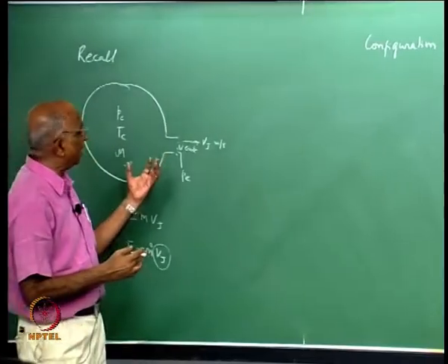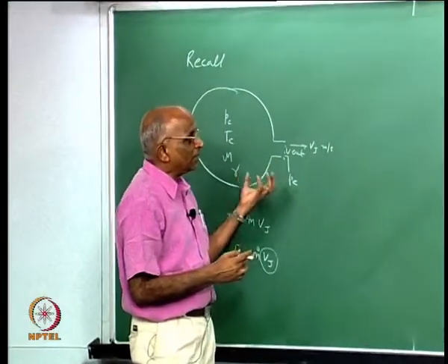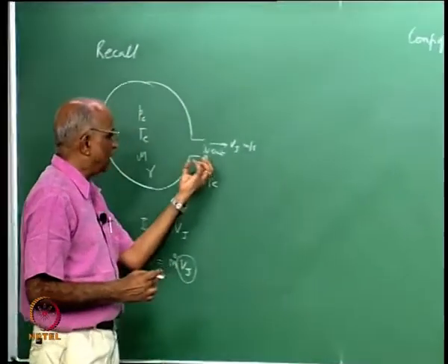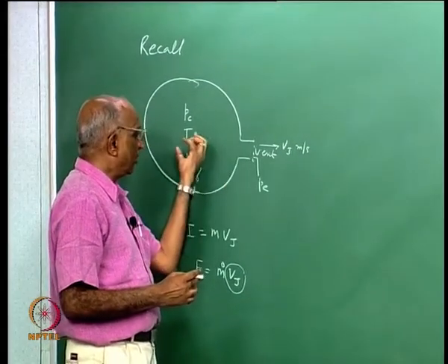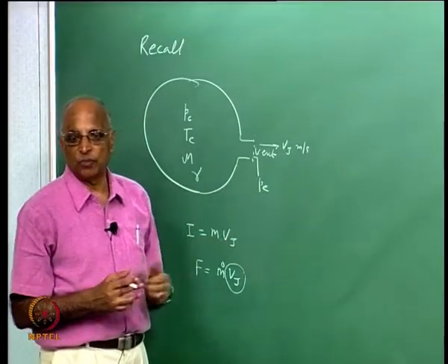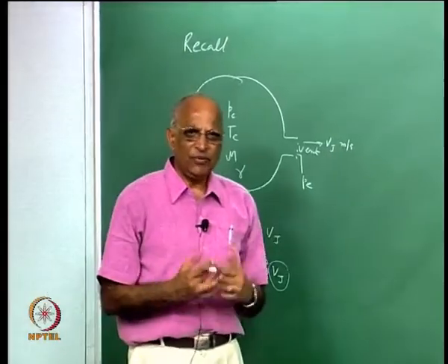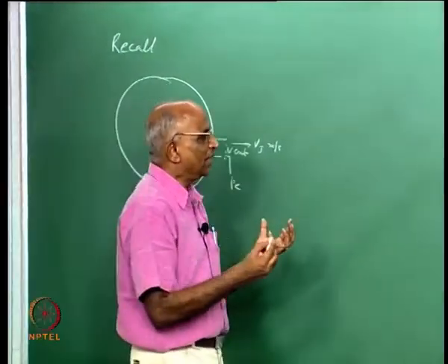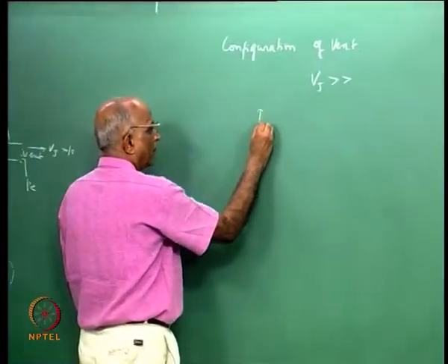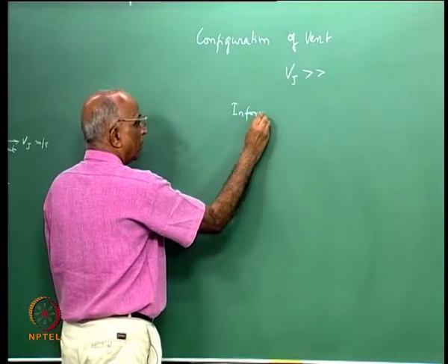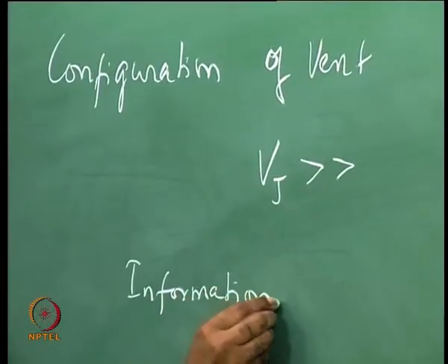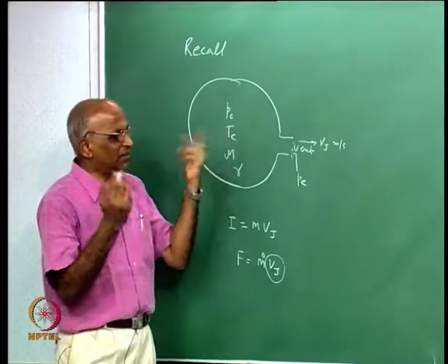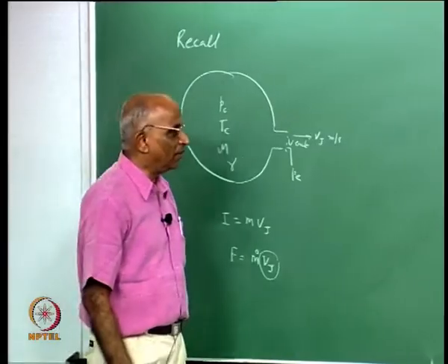Then we will go back and try to find out what are the conditions for this high jet velocity. We will have to look at matching of the exit pressure with respect to the chamber pressure, and that is what I propose to do in today's class. We will also physically try to understand, is there anything like some information transfer between the outside and inside of a chamber. Let's get started with this background.